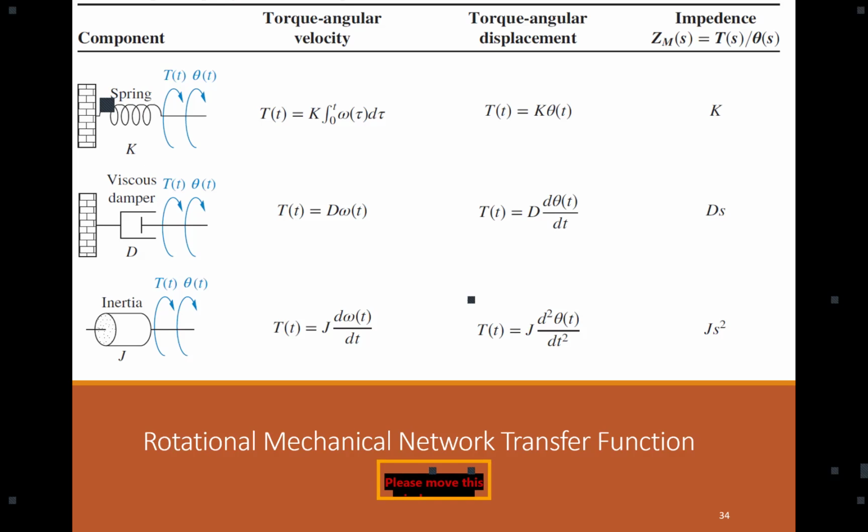So simply by controlling the velocity instead of the location, you multiply the whole system by s, meaning you eliminate that s, the zero in the denominator that happened to be at a marginal place for stability. So you have a more stable system. Makes sense? This is just a point, but we are going to learn what I mean by that later on when we talk about poles and zeros.